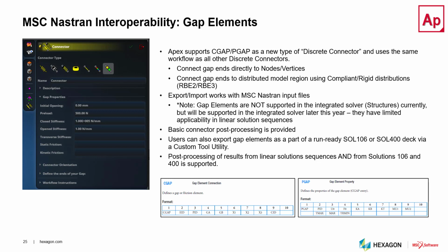Now, one little caveat to this is that gap elements do not work in the integrated solver. So this is basically an MSC Nastran technology that MSC Nastran users now have GUI support for pre-post capability. Now, this is if you are a legacy Nastran user for maybe Sol 106 or Sol 400. And you use gap elements, you're probably jumping for joy right now, because this has been a long-standing request from our worldwide customers, and we're very proud to deliver it to you now.